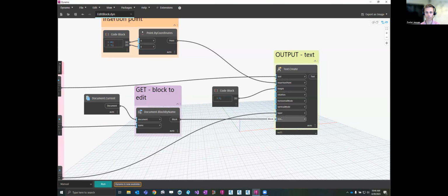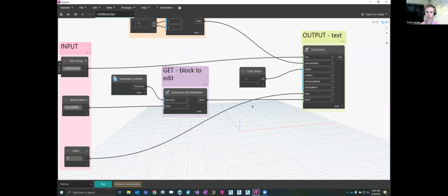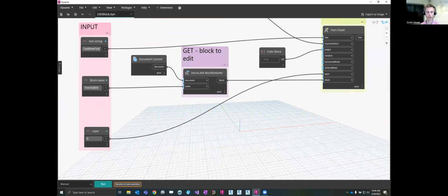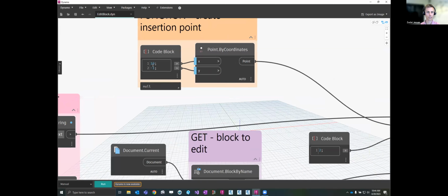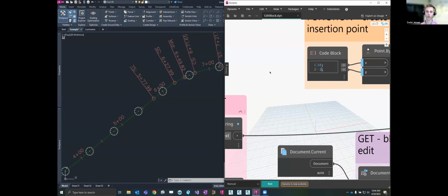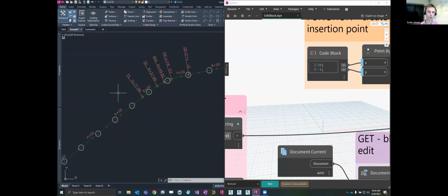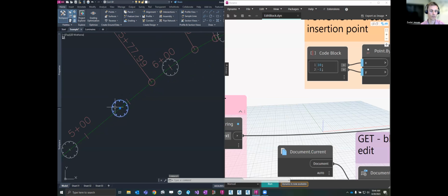Instead of putting that in model space here, which would be a common way to do it for this block input, that block is now going to be our tree block. And the coordinates I'm using, I placed it to make it look good, but just X and Y, it's just 10 and -1, which in world coordinates, in model space, would be very far away from our actual project, but we're working in the coordinate system of the block here.